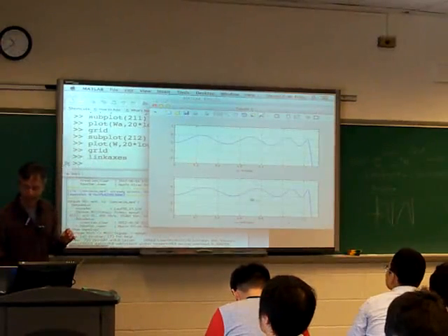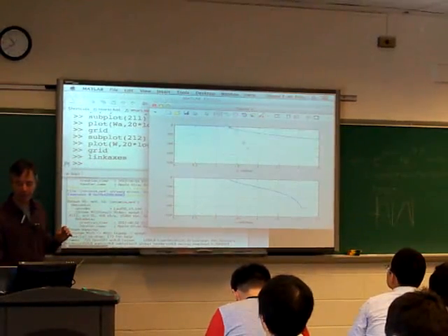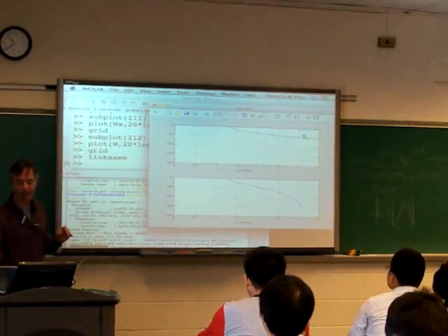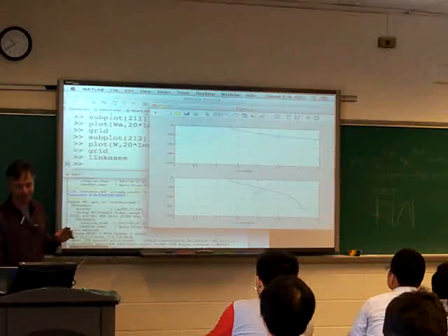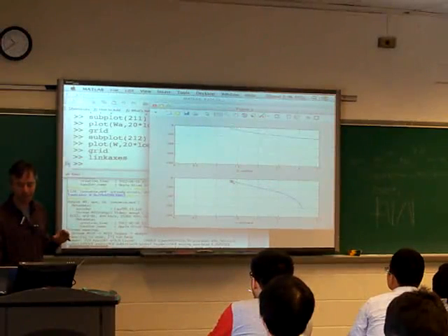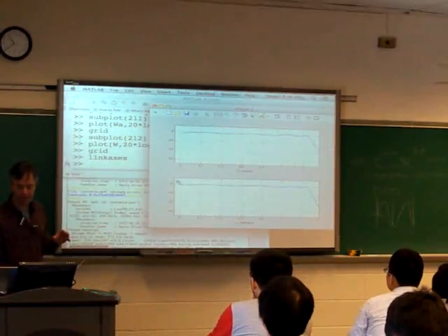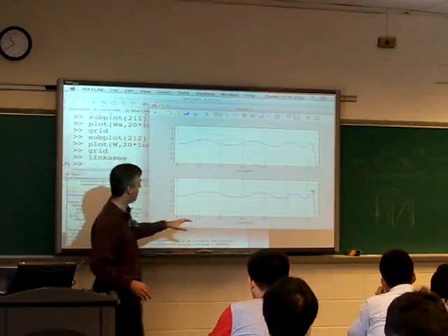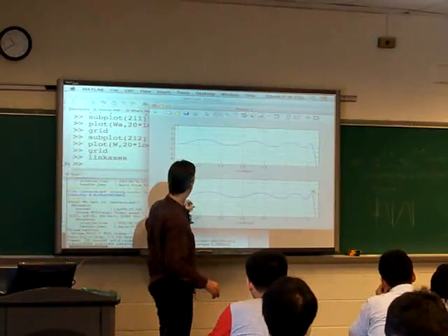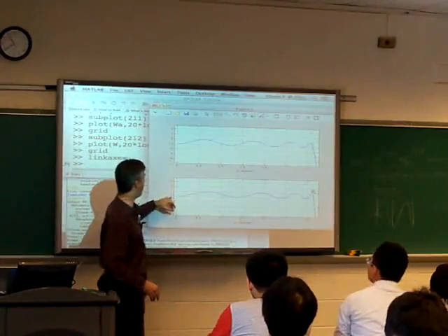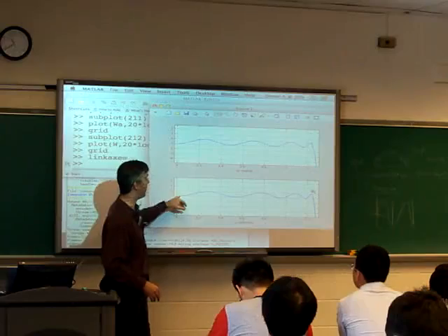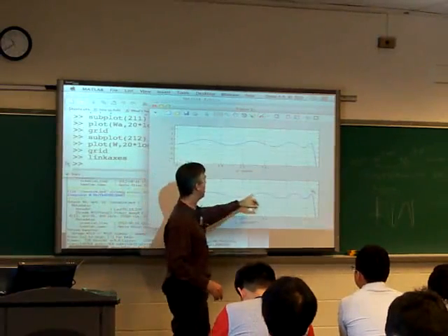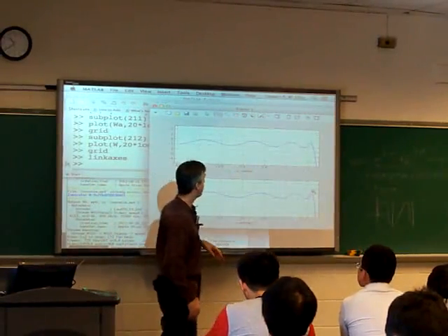So getting back to this plot, where I plotted the two filters, and I only plotted up to pi radians, and I'd normalized the frequencies. Now we can zoom in on these pass bands, and we see that against little omega, we have this 1 dB deviation, which was the filter design, and we have 1, 2, 3, 4 peaks in our ripples.